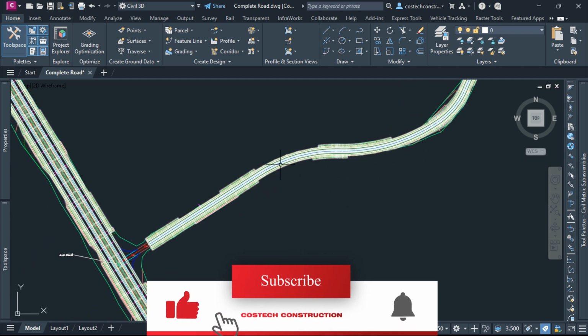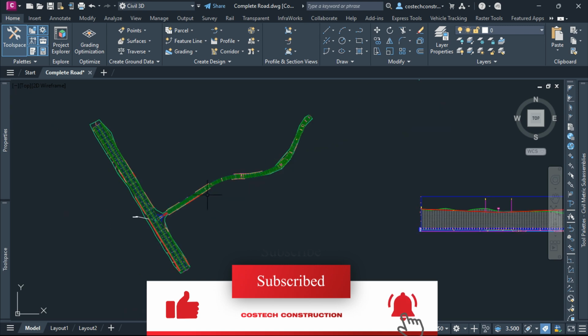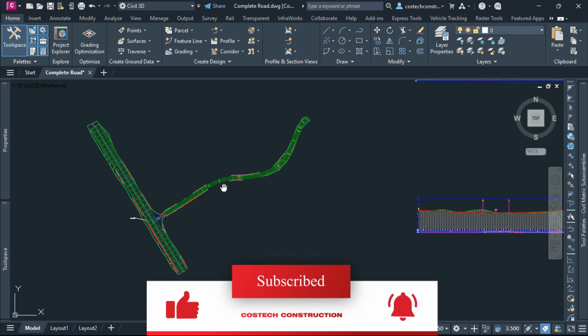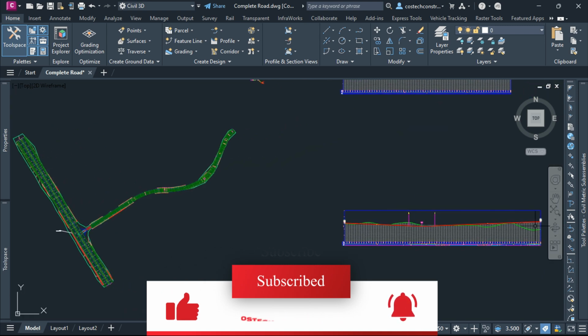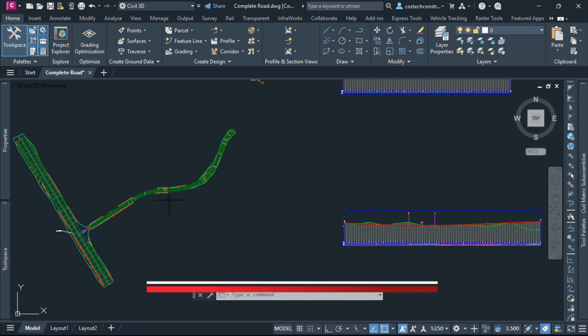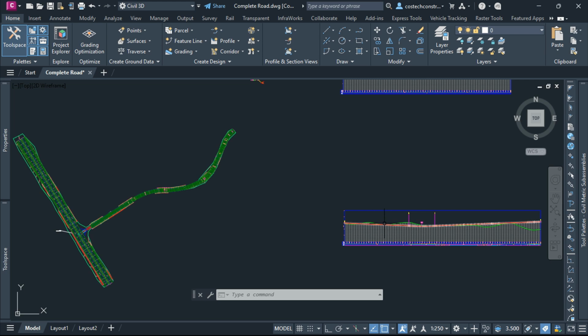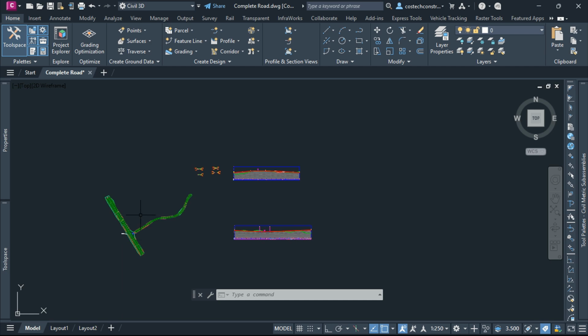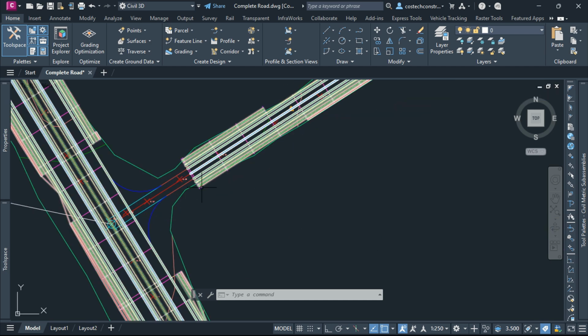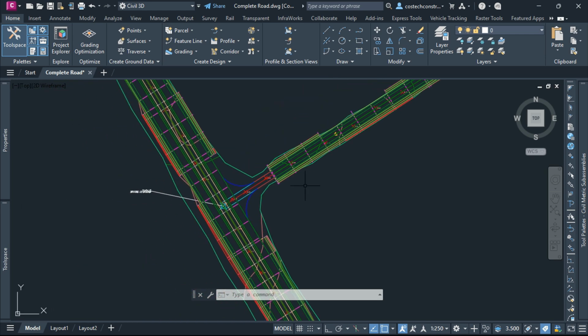Targets ensure that the secondary road aligns with the main corridor at both the horizontal and vertical levels. Road 2 profile controls the elevation of our corridor, which follows Road 2 alignment. The assembly used at the intersection terminates at the left offset, which also aligns with the curb return alignment.